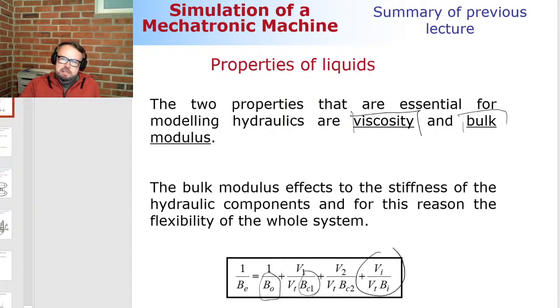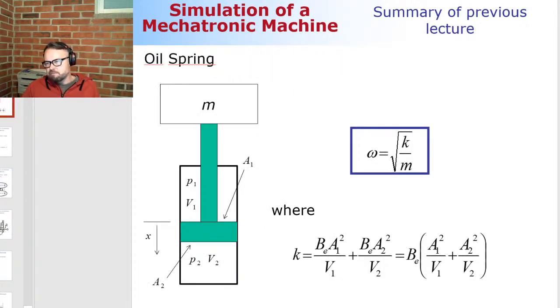Okay, this is what you need in this week's homework, last week's weekly homework. In last week's weekly homework, there was a simple hydraulic-driven crane, and it was asked what the lowest natural frequency of the structure is. In that particular case, the flexibility is assumed to come from the hydraulic cylinder only. The natural frequency you can, of course, compute as the square root of stiffness divided by mass. So that's an equation you need.